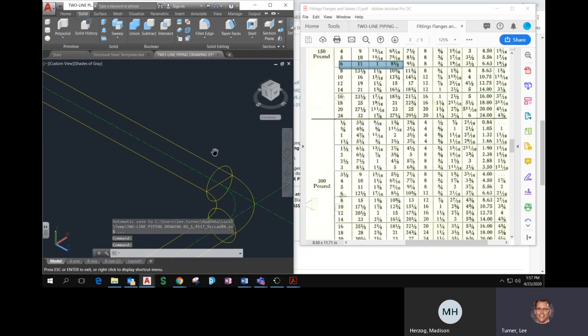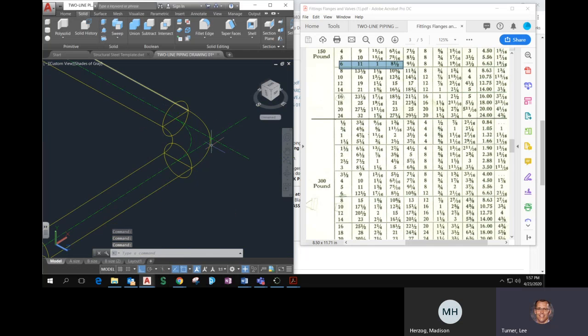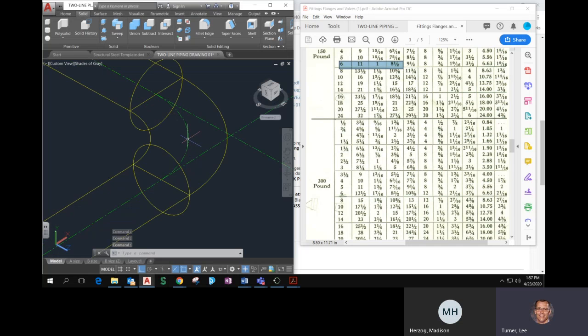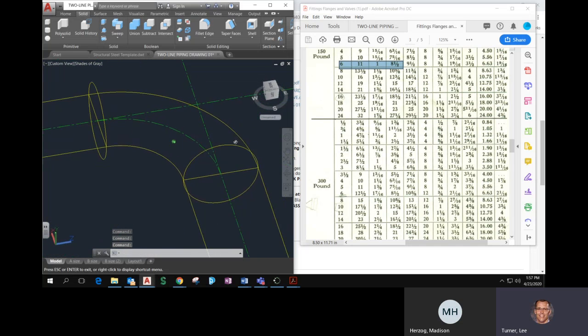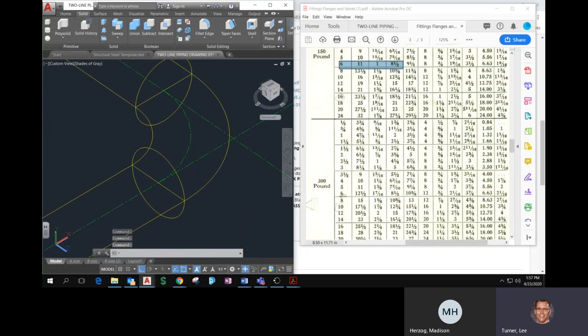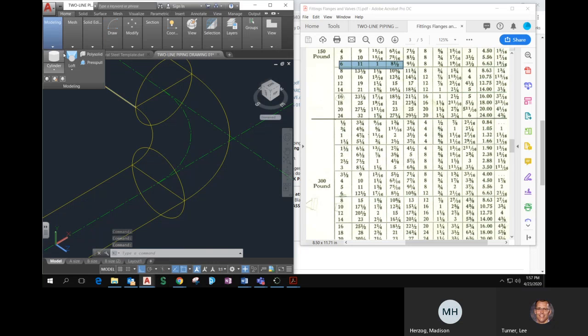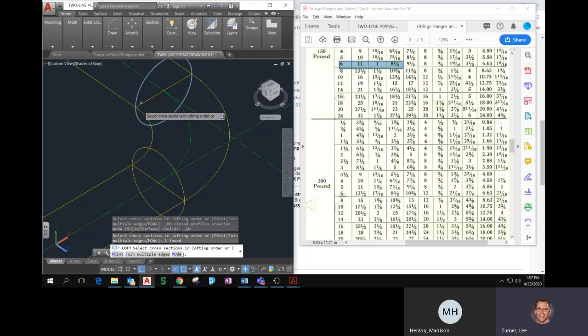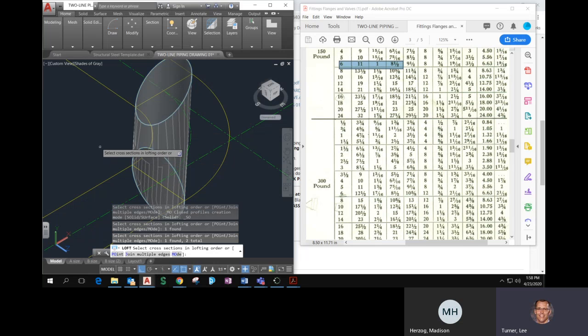So anyway, there you go. And then there's another tool down here, you could revolve or loft. But let me go ahead and show you, because I can't help myself. A student showed me this one time, because, again, you could revolve it and make this elbow, or you could do this. Loft, pick both of the cross sections, and it'll make a straight loft, just like that.